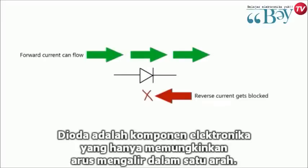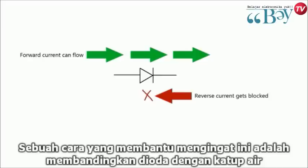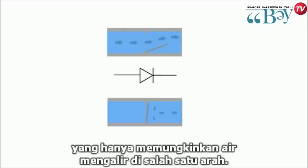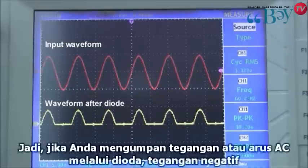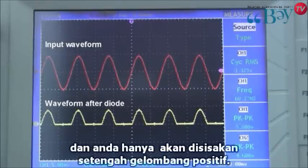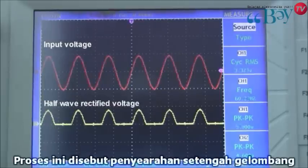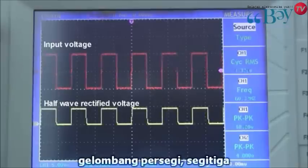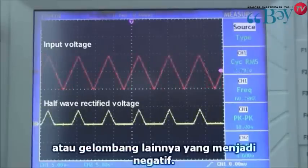A diode is a device that only allows current to flow in one direction. A helpful way of remembering this is to compare diodes to water valves that only allow water to flow one way. So if you feed an AC voltage or current through a diode, the negative voltage will just get blocked off, and you'll be left with only the positive half of the waveform. This process is called half-wave rectification, and it doesn't have to be with just a sine wave. It'll also work with square waves, triangle waves, or any other waveform that dips into the negatives.